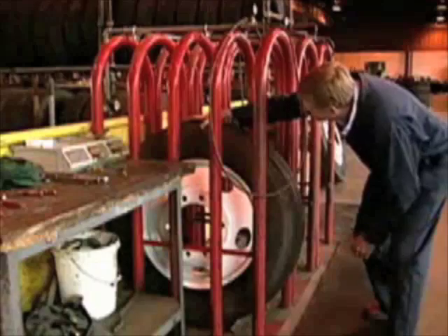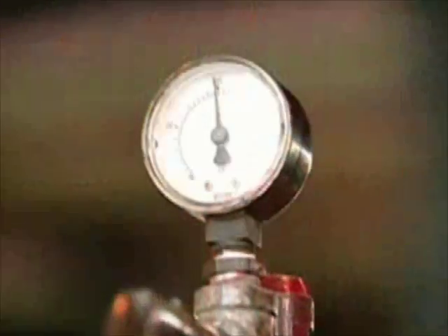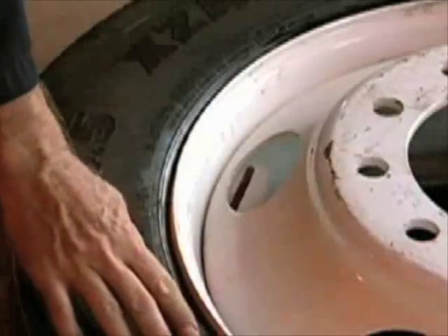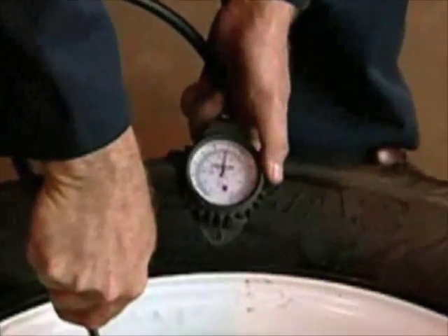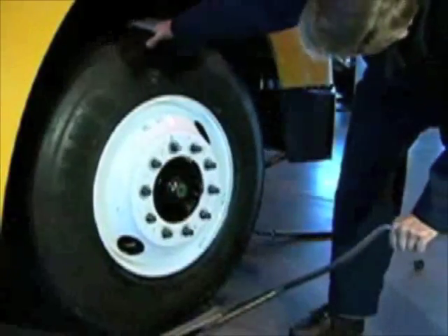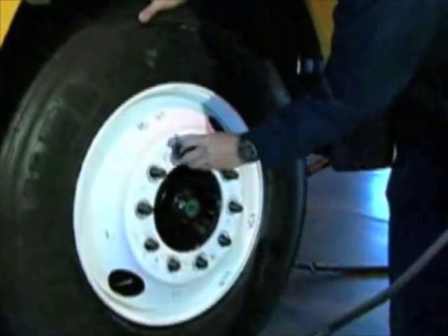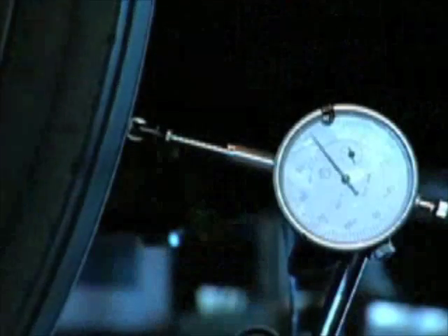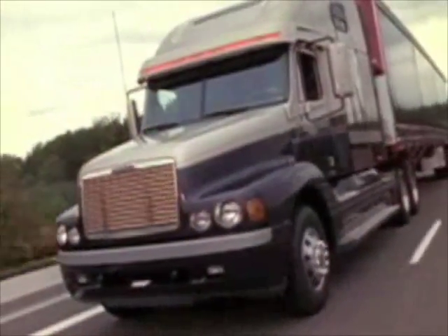After having checked the assembly carefully for any apparent signs of weakness or irregularity, continue to inflate to the maximum air pressure marked on the sidewall. Visually check the beads for proper seating. Adjust the tire pressure to the recommended operating pressure, check for leaks, and then install a suitable valve cap. Mount the assembly on the vehicle using the techniques we have covered in this video to minimize runouts. With the assembly now within runout tolerances, you will be assured of a smoother ride.